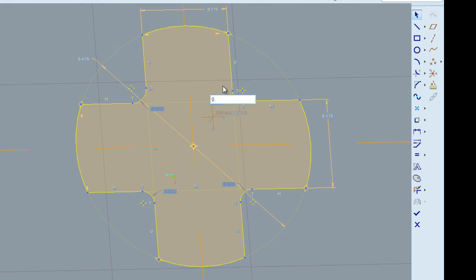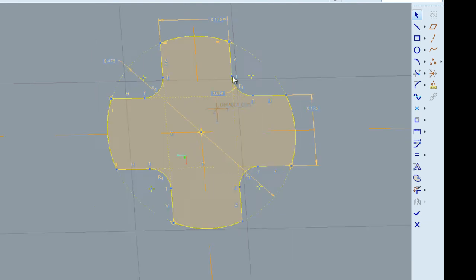Now, our diameter, if you measure from one of the axles, is 0.1. So our radius is then 0.05. Click Enter. And then we'll also use the equal tool, so set these all as the same radius. So you see we have tangent, radius 1, tangent, radius 1. So our radius 1 here. And with that,